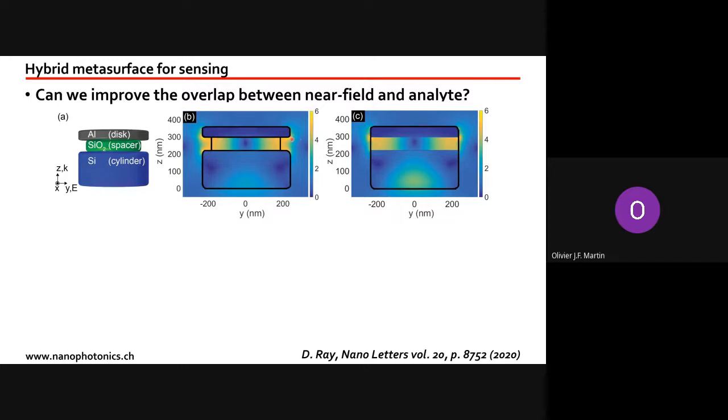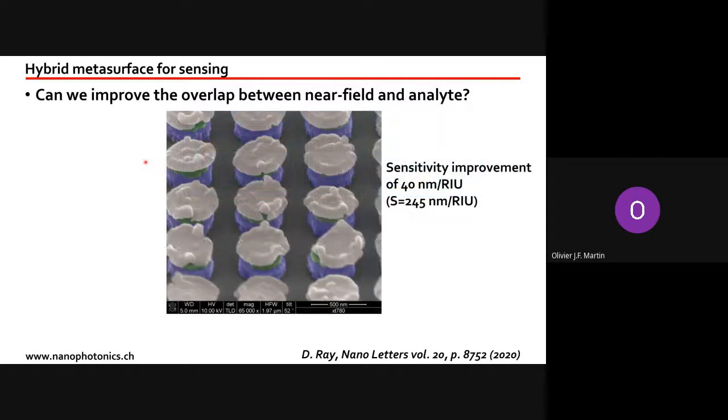And we see that if we etch a little bit this glass disc, then we can access, in that case, the outside world. The field becomes strong here in the background. It was possible to do that by having an additional wet etch step, and then we would etch away just the glass. It would not etch the aluminum or the silicon. And this is what it produces.